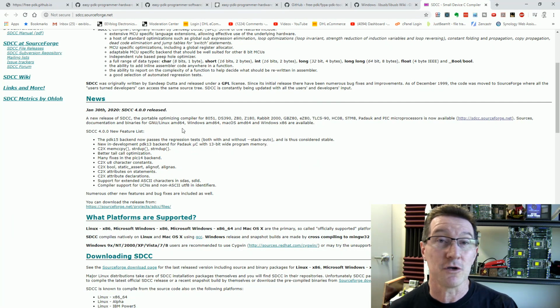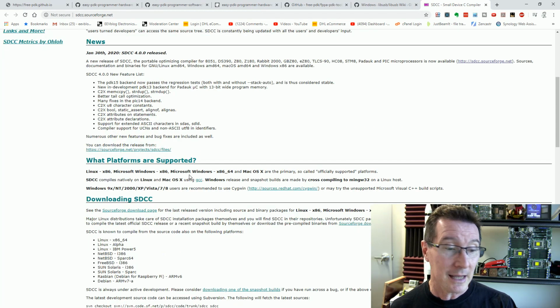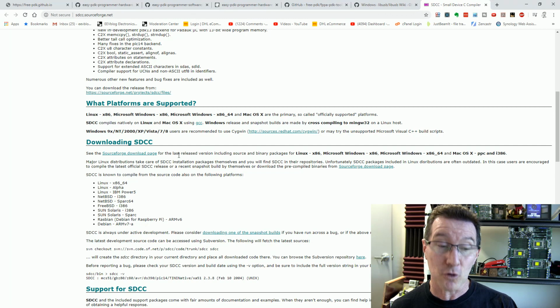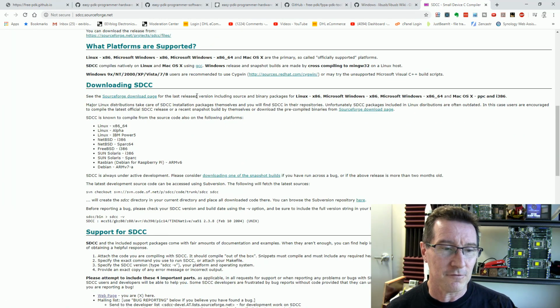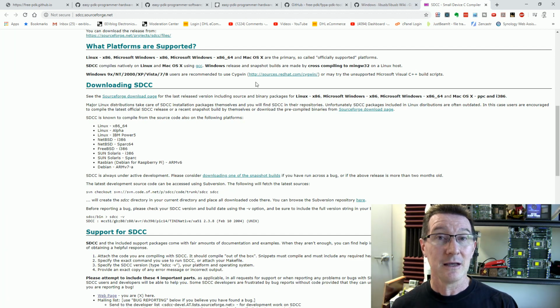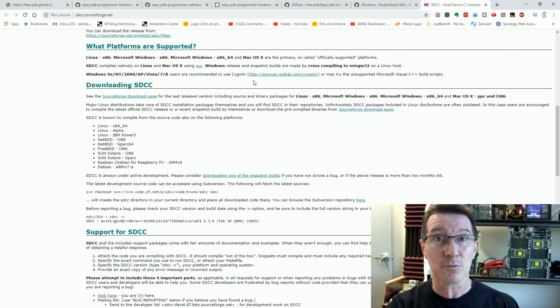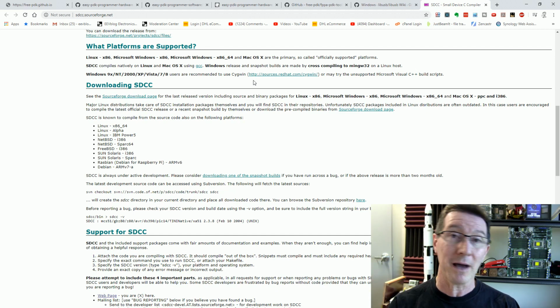So use your favorite Notepad++ or whatever you want to use to write your actual programs in, and then you can just call the compiler. There are probably various scripts and things you can do to automate all sorts of processes. But the general thing is, you write your text file containing your C program, you run it through the SDCC compiler with a specific target for whatever Padauk microcontroller part number you're using,